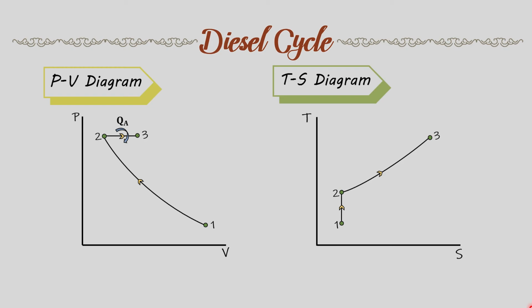At the constant pressure phase, combustion occurs as the diesel fuel is injected or sprayed into the cylinder with pressurized air, which adds heat to the system. Looking at the diagram, the pressure remains constant while the volume is higher because of the fuel injected or sprayed.